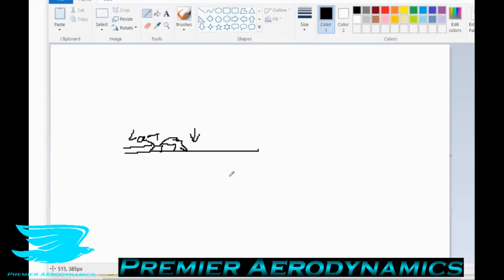So what this means is if we have the surface, whatever it is, we'll usually get an LSB forming here at 35% downstream from the leading edge. If we put the trip at 10%, the turbulence that it creates by the time it gets to the laminar separation bubble region will dissipate and the flow will still stay laminar. If we put the boundary layer trip further downstream at 17%, now the turbulence that it produces is enough to stave off that LSB formation. Now, hopefully the boundary layer will transition to turbulence completely, but not necessarily.